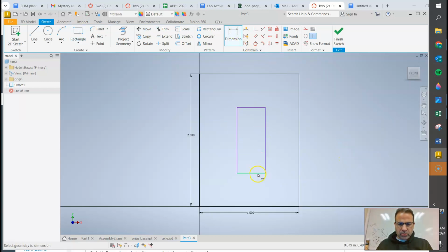The dimension across here, this is the critical dimension. This should be 0.13 inches approximately. That's the thickness of the wood. This dimension right here can be whatever you want. I'll make it 1 inch. A lot of people are asking me, how do you put this in the center? Well, you need dimensions to put it in the center. You can see that dotted line right there.